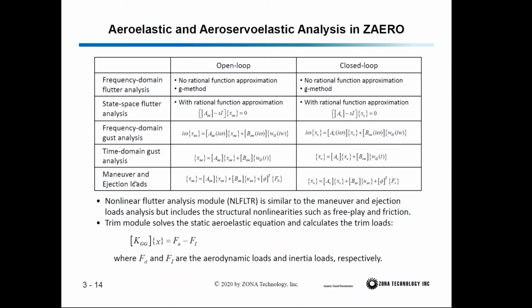And we can perform maneuver and ejection loads analysis for both open loop and closed loop. We also have a nonlinear Flutter analysis module, which is similar to the maneuver and ejection loads analysis, but includes the structural nonlinearity, such as free play or friction.